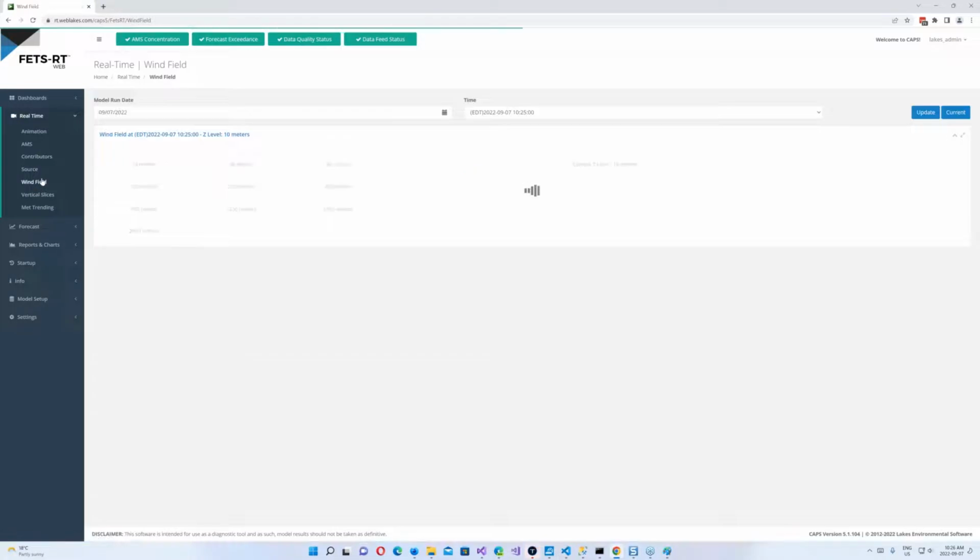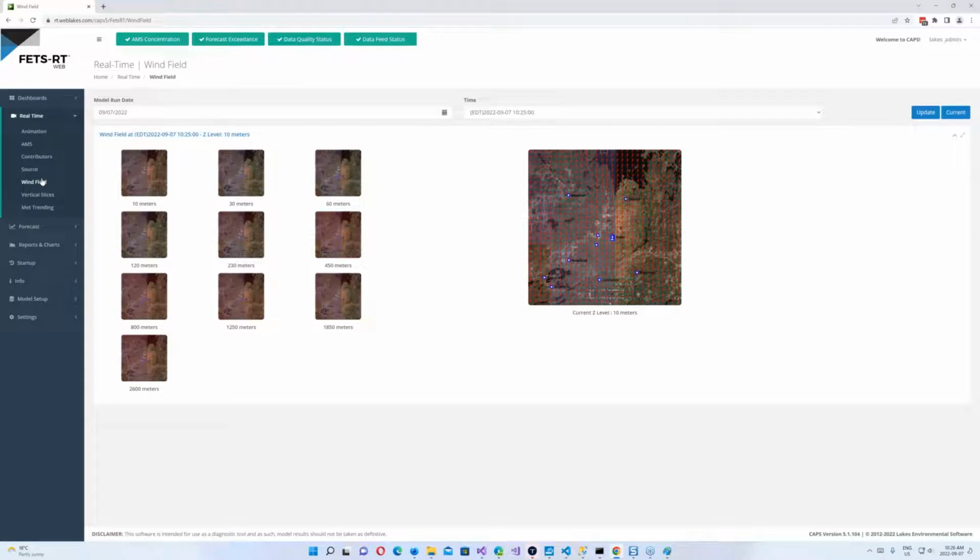We can look at things like the wind field, as Dr. Jesse explained, because we are using a model like CalPUF, and the multi-level wind. We can see that, for example, the wind is blowing north here at the ground level, but as we go higher up, because there's less friction, we can see that the wind is now progressing from the northwest to the southeast. So you can see this quite handily and readily. This just allows us to see, for example, if we have a very tall stack, why the plume is going in a particular direction as opposed to lower level sources such as fugitives.